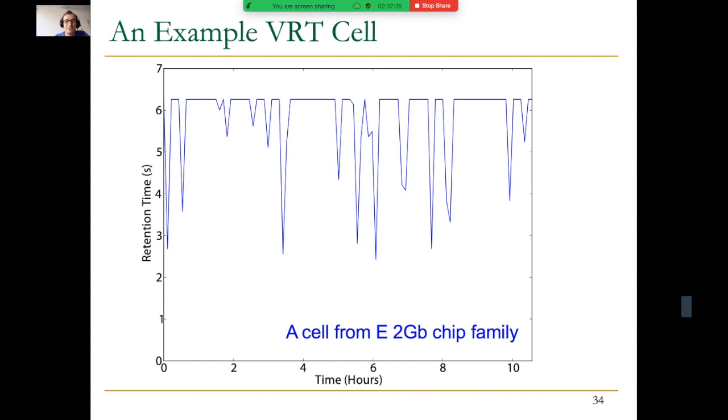Okay? So that's interesting. At high temperatures, there's a temperature dependence. As I said, at high temperatures, circuits become more leaky. And we've shown in our paper that as you increase the temperature by 10 degrees Celsius, you reduce the retention time by 46.5%. And this is very predictable. You can look at our paper. There are curves from real devices that show that that's real, which means that temperature reduces the retention time exponentially. Right? At 85 degrees Celsius, all of these seconds become milliseconds, hundreds of milliseconds. Now, if you want to go to 100 degrees Celsius, junction or operating temperatures, that becomes even lower, right? Okay, so you've got to be careful about temperature, clearly.